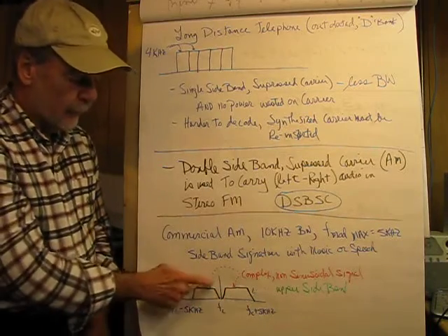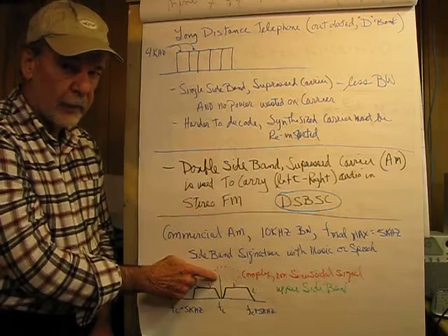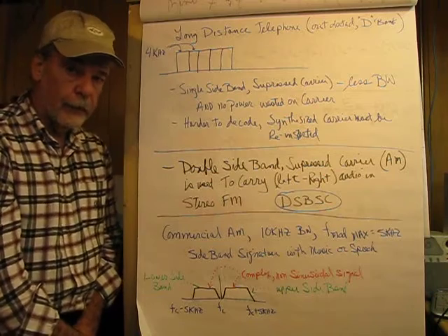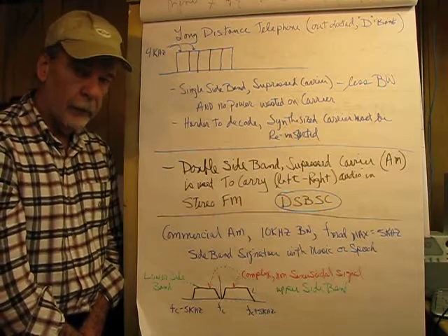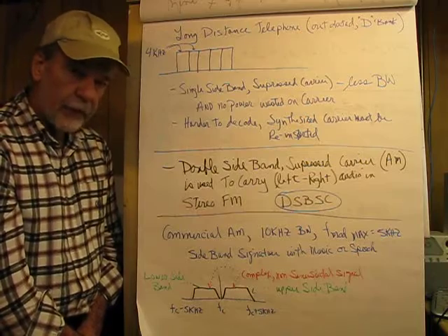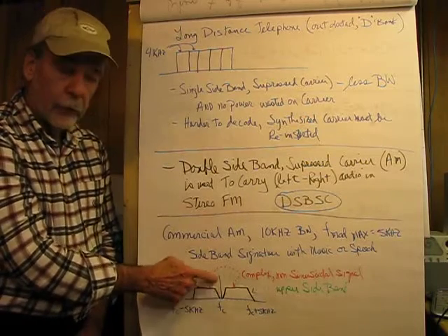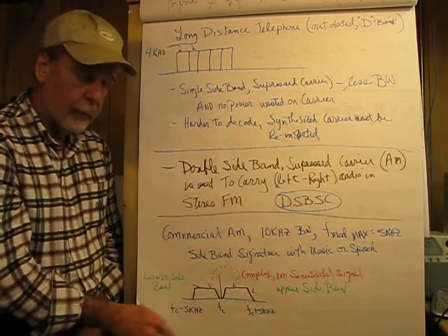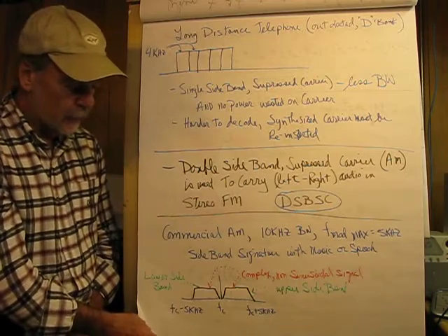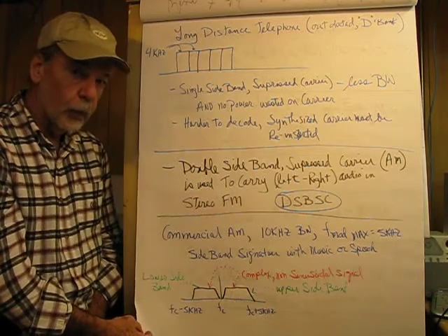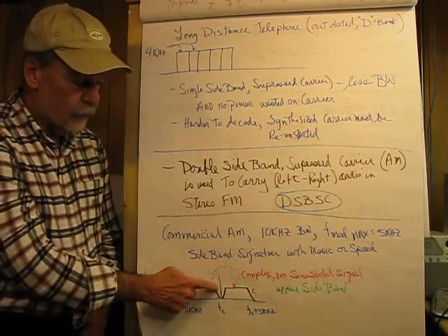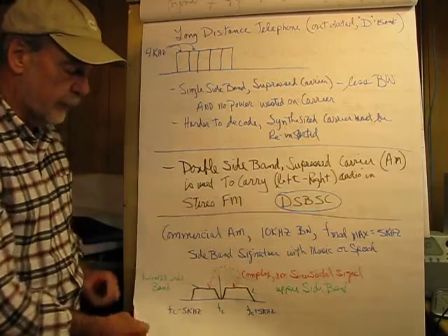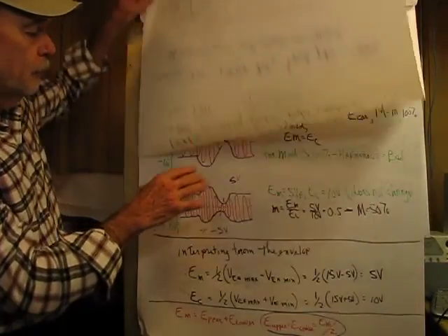Now, important, the carrier never changes amplitude with modulation. It's always there. Case in point, when nobody's speaking over a clear channel AM station like WTAM, 50,000 watts sits there and burns. Carrier's present. Does not carry information, but standard AM needs that for the receiver. So they've got a power meter spinning around out there that really isn't carrying information. This is not true in FM. In FM, sometimes the carrier is 0, but that's a whole different modulation method.